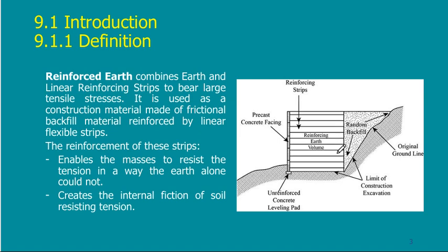Why not? Because I'm using the soil, the soil that is in place, or even if I import it from outside, it is still very cheap concerning any construction. And I'm just using a facing, a concrete facing, or maybe it may be made of any other material, just a simple facing, plus these lines. These are the reinforcing systems that are included to make the facing and the mass of this soil work as one piece.